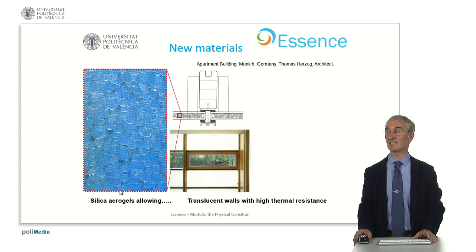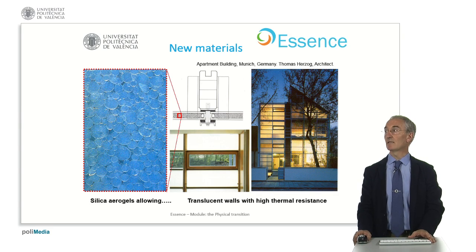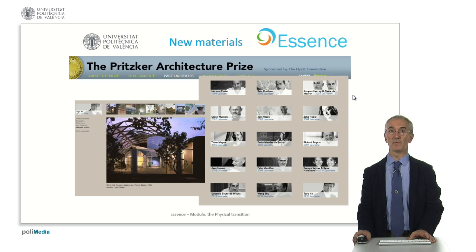Introducing materials such as silica aerogels in this apartment building is really intelligent, because once the life is finished for the building, we can reuse these sub-elements, or we can even take the whole lot and use it elsewhere. It provides a good solution for lining, so this is a very nice integration and development of a hybrid material. Be careful with the thermal bridges on the building, but all in all it's a good solution, which provides an aesthetic approach to the building.